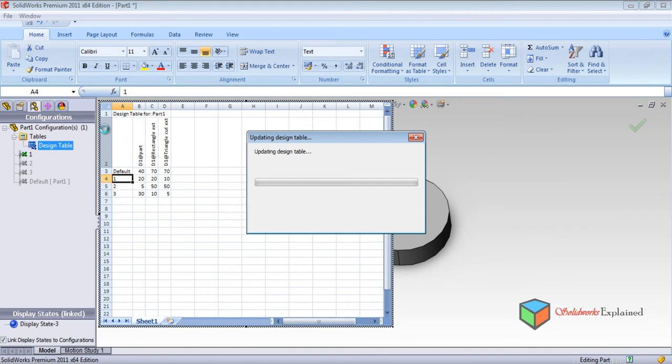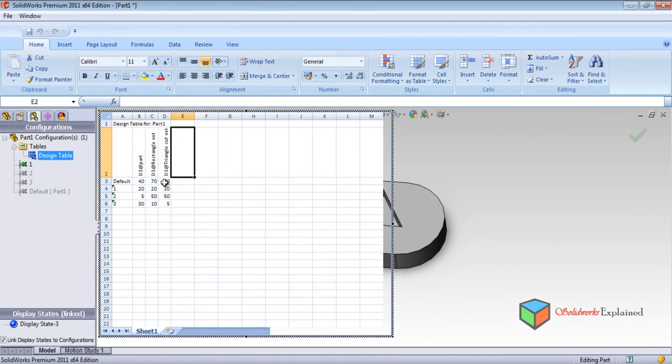So you really need this thing. For example, if your boss says make 10 different designs and show me, you can just vary few constraints, you can select from the constraints, and then you can really show, okay, first design is this, second is this, third is this. Now you select which is the best, rather than making 3 different designs again and again, then copying the part and then again editing the part and then saving 3 different files. So this is a lot of work which you are doing. To avoid this kind of work, this design table proves to be very efficient.